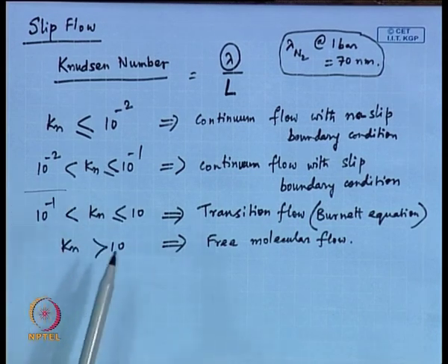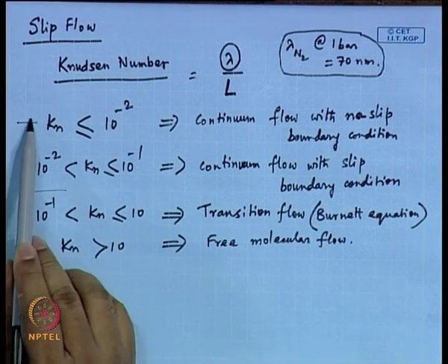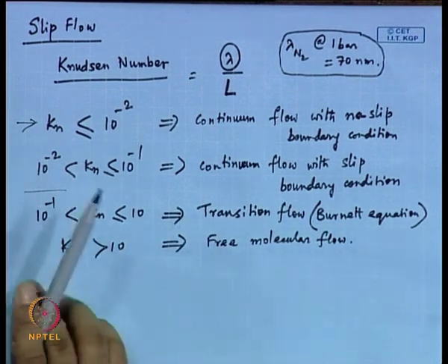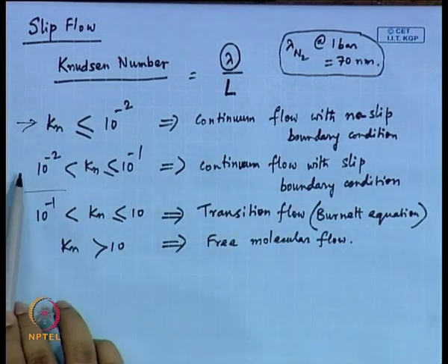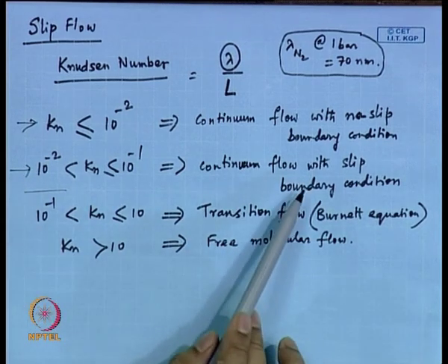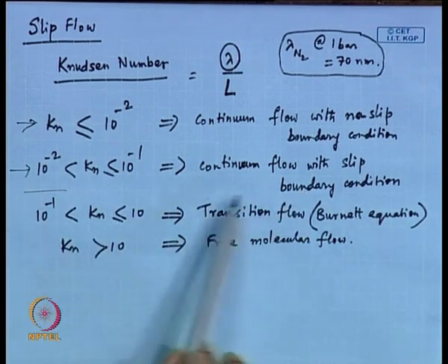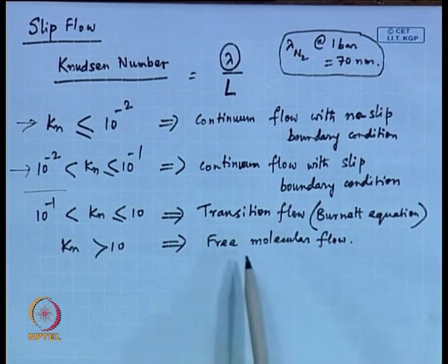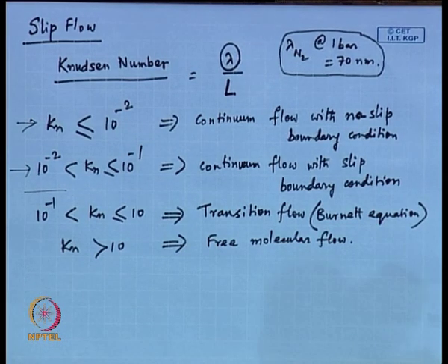This part, continuum flow with no slip boundary condition, you have studied time and again in fluid mechanics and transport phenomena everywhere. So, this I am not going to talk about. This part I am talking about, continuum flow with slip boundary condition. This is the ultimate free molecular flow, this is how you should be simulating it. But for free molecular flow, you understand how much computational effort would be needed just to simulate an event for so many seconds. Just tracking each and every molecule requires a huge amount of computational effort. So, you cannot afford that.